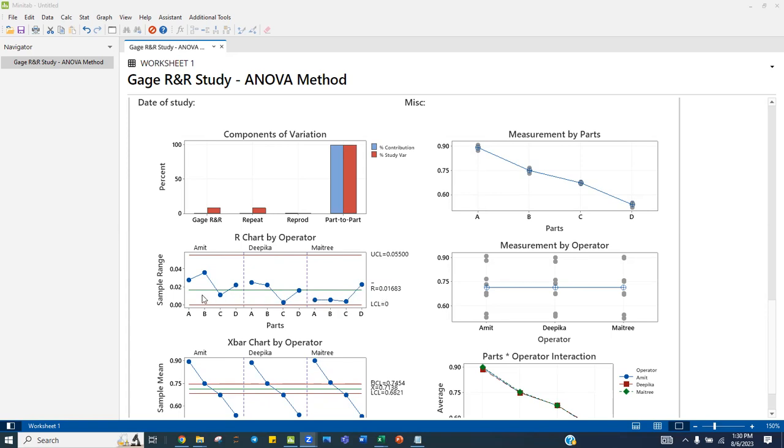They are not able to repeat their exact result, but still, because your range variation is very low, the repeatability of approximately 8.15% is understandable and within our acceptable limit, as the max limit is 30% for the sum of the repeatability and reproducibility. And if I see the reproducibility variation, it is very minimum, almost zero.